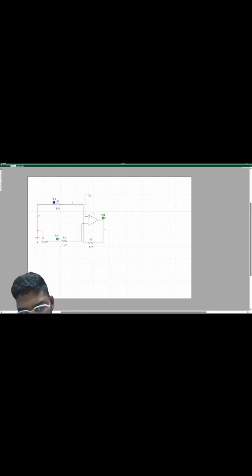Analyze and record the voltage drops and current flow in both on and off states to confirm the expected operation. Ensure components are connected correctly. Parameters, for example resistor values, are suitable for the given supply and LED rating, and observe brightness and switching response in simulation.